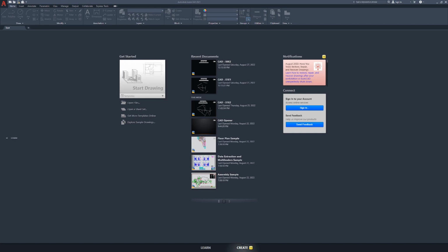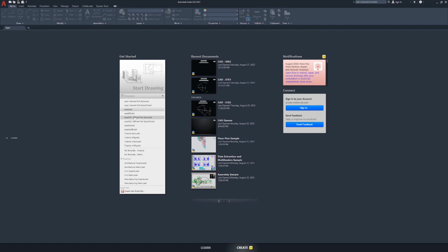This is going to be a quick video on how to get yourself moving from nothing. So the first thing we're going to do is click Start Drawing, or if you have a different template that you want to use, you can click the drop down here and choose a different one. For this video, we're going to use the AutoCAD.dwt normal English feet and inches drawing template.